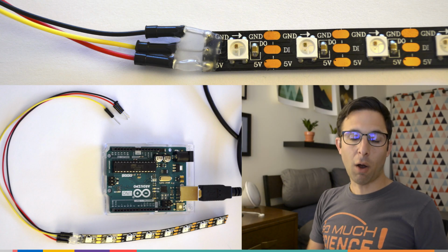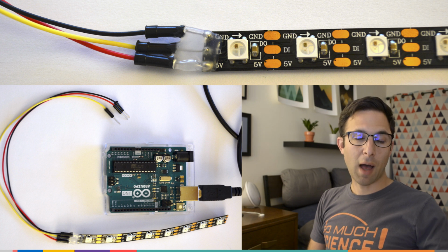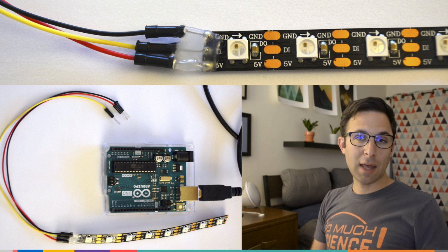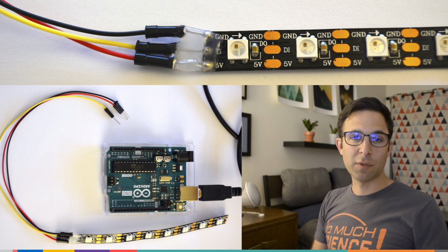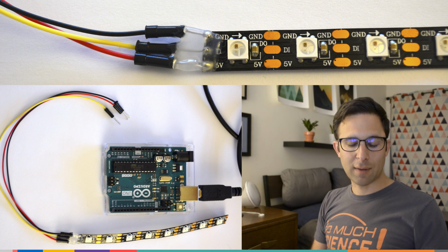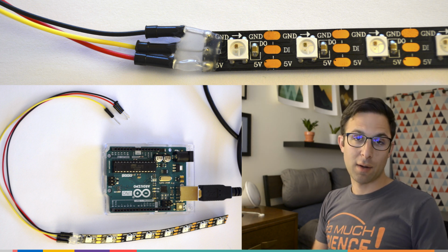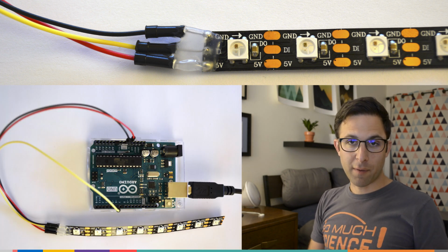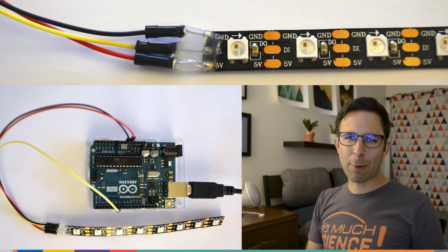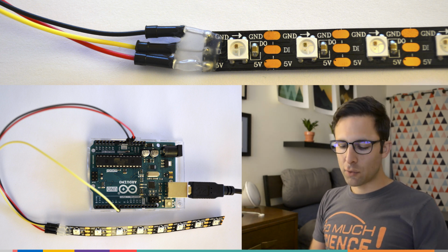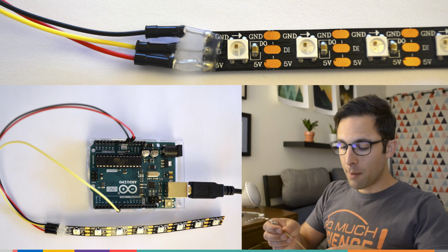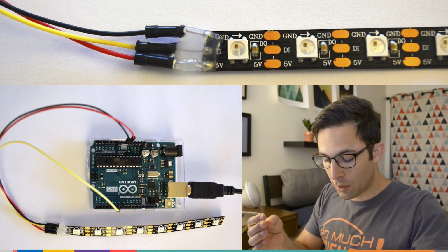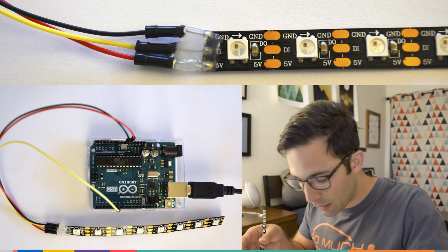There are 4 parts to this LED. There's basically the high voltage side, the 5 volts. There's the low voltage side, the ground. Then there's a data in where all of that information about the colors comes in. And there's also a data out where the LED sends the remaining information on to the next one down the line. And we are able to provide that power from the Arduino as long as we're only powering about 8 LEDs. And so there's a few different ways you can hook it up, but you'll take the wire connected to 5 volts and you can connect it to the 5 volt pin on your Arduino.